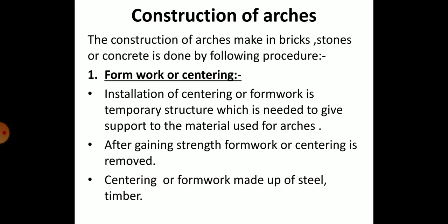The installation of centering or formwork is a temporary structure which is needed to give support to the material used for the arches, and after gaining the required, sufficient strength, the formwork or centering is to be removed. The centering or formwork is made up of steel or timber, and timber centering is simple and cheap and is generally used for moderate spans. It can also be reused many times, and it is simple and easy to install.